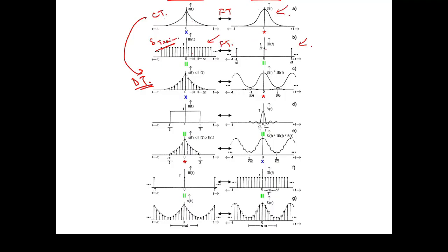As soon as we get this discrete time signal and perform the Fourier transform, we get frequency components where the original frequency component is repeating itself. Why? Because in the time domain we have multiplied, however in the frequency domain it gets convolved.